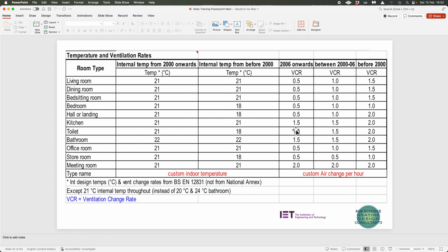It heats the whole house and brings the thermal mass of the building up to quite a high temperature quite quickly. But these are the rates that we would work on for longhand calculations, and this would be the only one that changes as we move forward in this final equation of a longhand heat loss calculation.